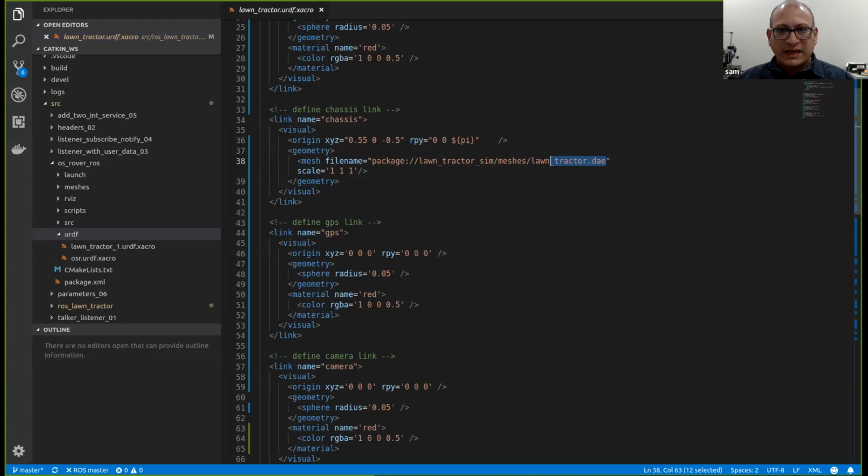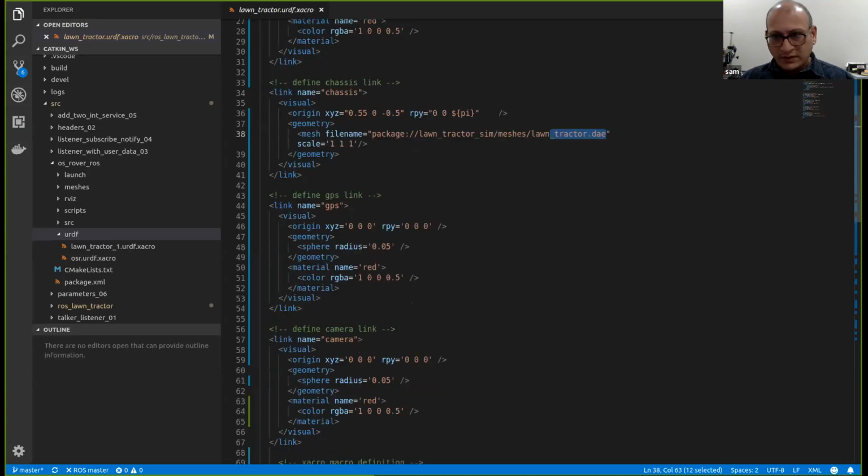Most of the time, what you're probably doing is just the translation of the CAD model, or scaling it, or if you don't like the origin, setting up the origin and then translating or converting from one format to the other. I usually use the neutral formats. For me, DAE is kind of a new format. FreeCAD has crappy support for the DAE file. So I started using Blender for the formatting and the initial translation and rotation, since Blender has wonderful support for DAE, but you have to use the new version to open up that model if you have DAE.